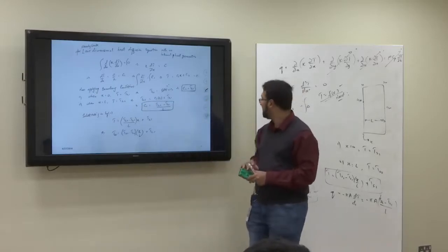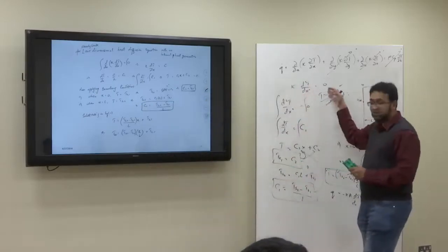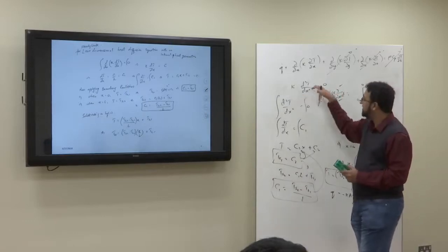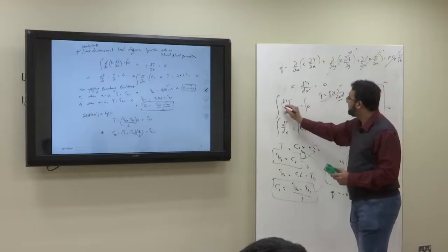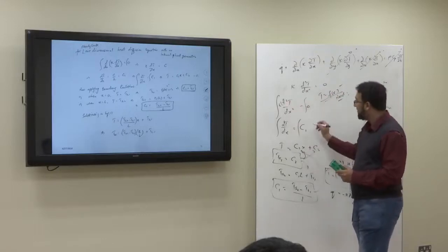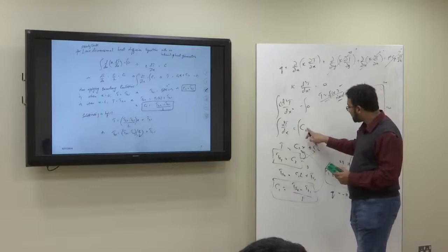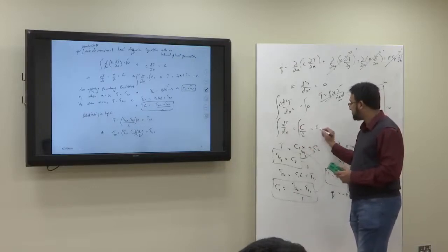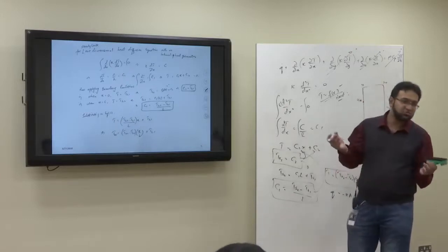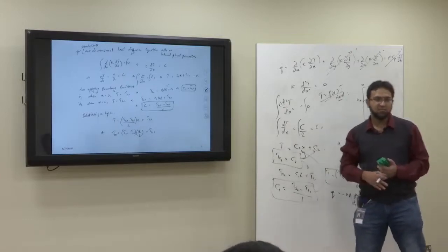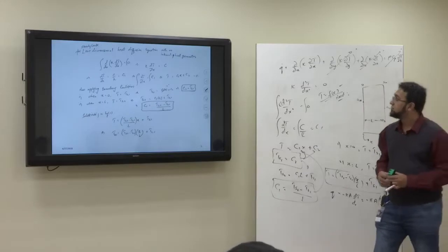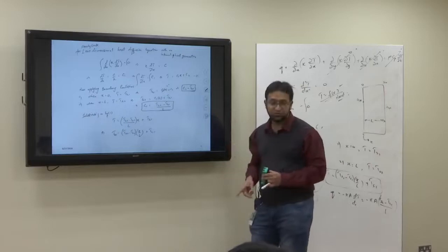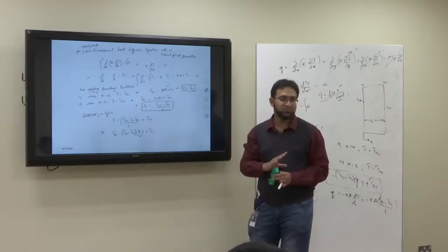What happened to the k? Either you eliminate k from the beginning, because this thing equals 0, or if you keep k here, a constant C will come. Say that C upon k is equal to C1. It doesn't matter, because k is also a constant. So this is the steady state one-dimensional heat diffusion equation with no internal heat generation.